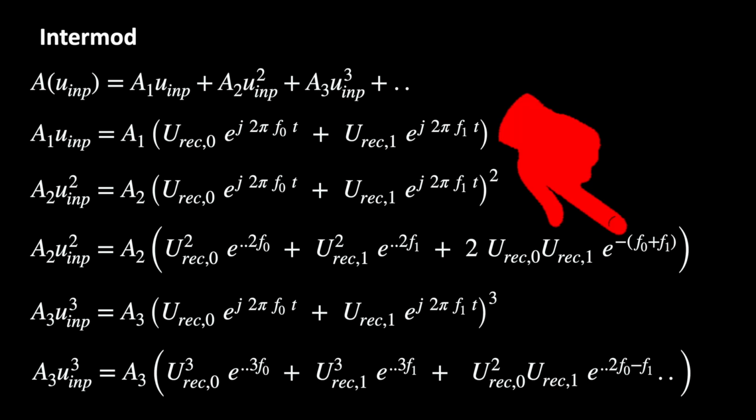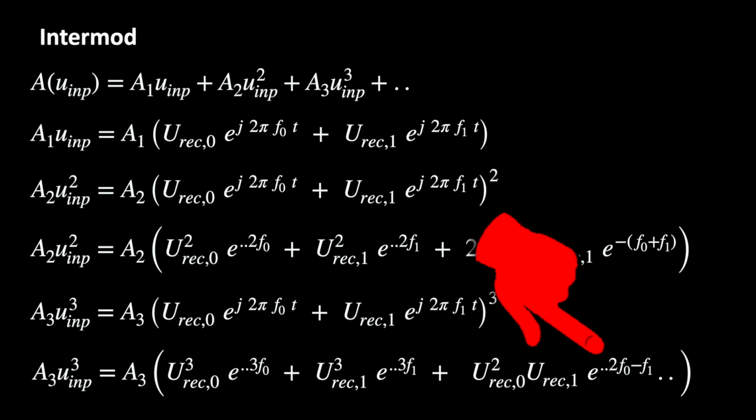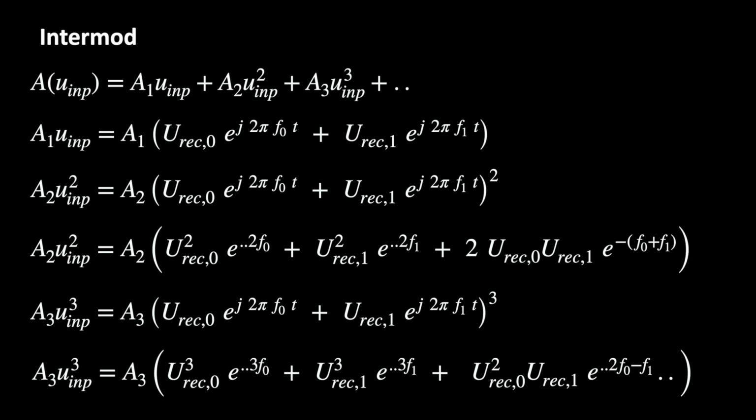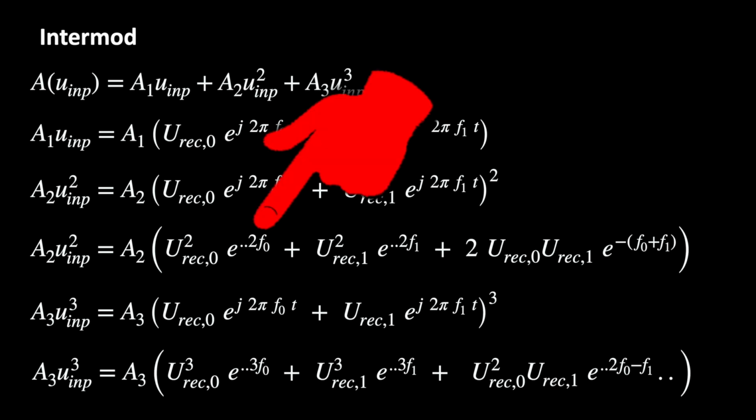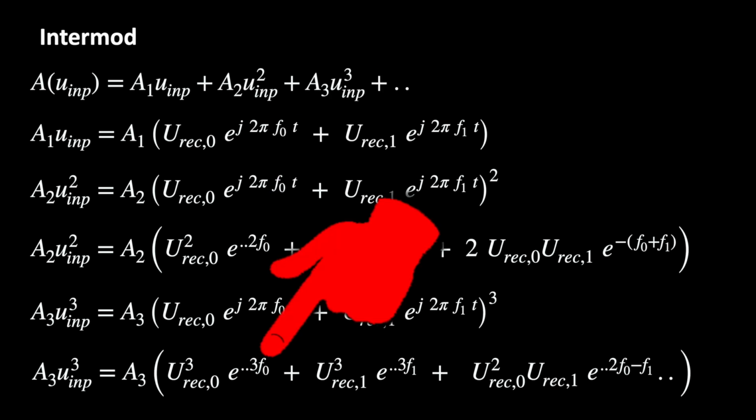There is a mathematical proof for that. The principle is used for receivers as well as measuring devices, such as spectrum and vector network analyzers. The non-linearity of our preamp is actually mixing signals. The principle even applies obviously when you are mixing several modulated signals. In case of harmonics, however, things are a bit different. We need to discuss that in more detail in a separate video.